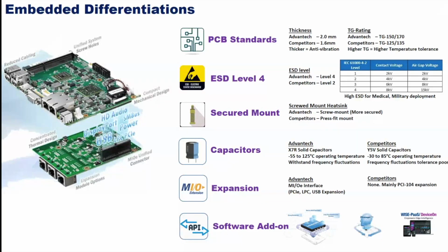When you use level 4, for embedded applications, sometimes you may be using it for certain sensitive deployments, like say rolling stock. For rolling stock, you have things like EN 50121-3-2, or even worse, -4, which is more for signaling. Those are very particular about ESD level.